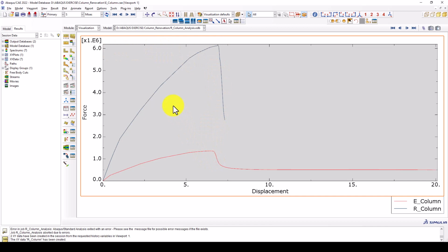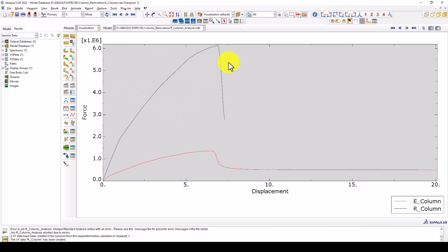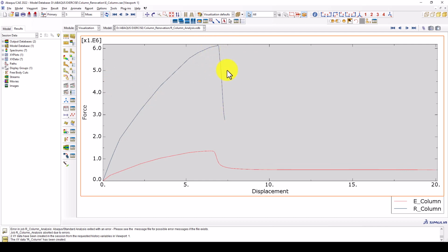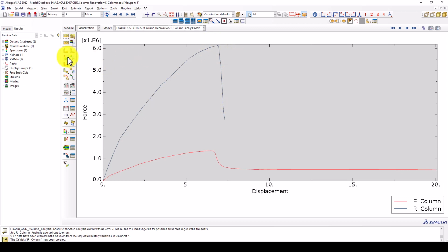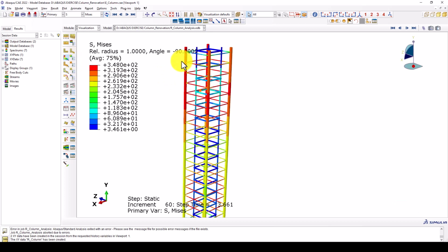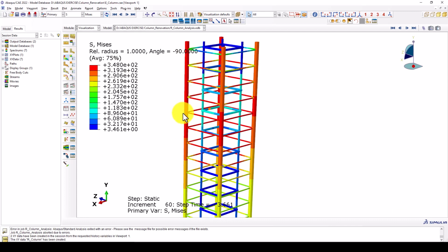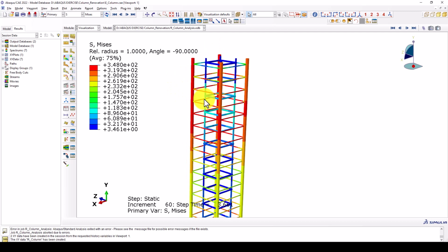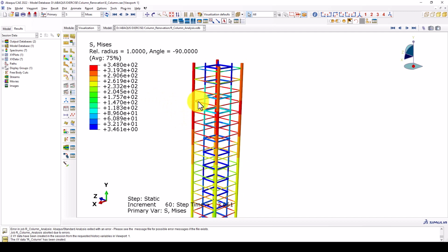In case we have some movement in the structure, there will be some other effects. But mostly the first damage is, as you can see, in this area. So when this rebar yields, the concrete compression phase is significantly reduced, and therefore the deterioration part is quite large.